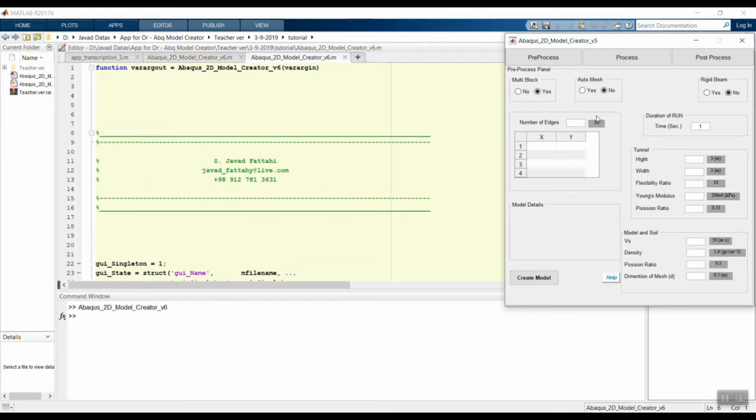This plugin can model linear 2D underground structures in the Abaqus finite element software. With this application, we don't need any previous knowledge in modeling, designing, running, and also extracting data fields. You can create a soil-structure model which is 2D, homogeneous, and has linear behavior. As perceived, it encompasses the interaction subject and also has an infinite medium assumption for soil under the shear wave field of motion with vertical incident angle and regular mesh dimension.